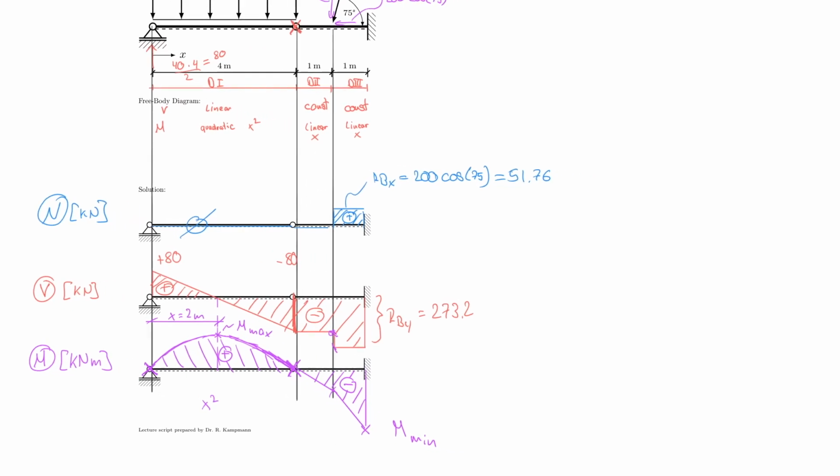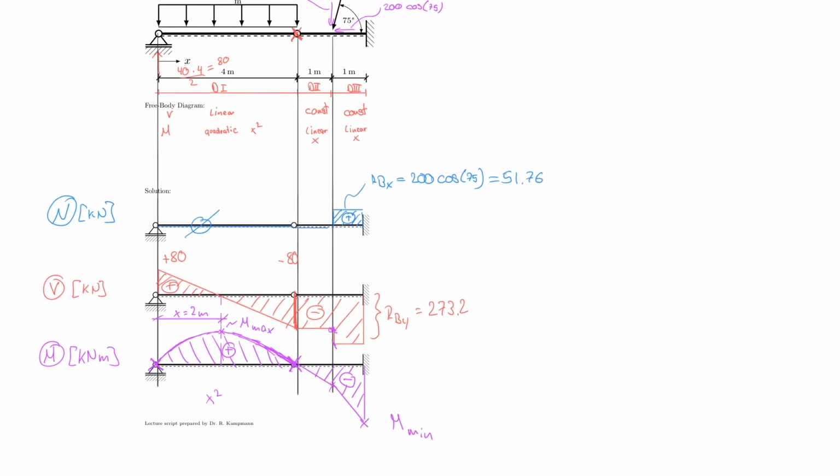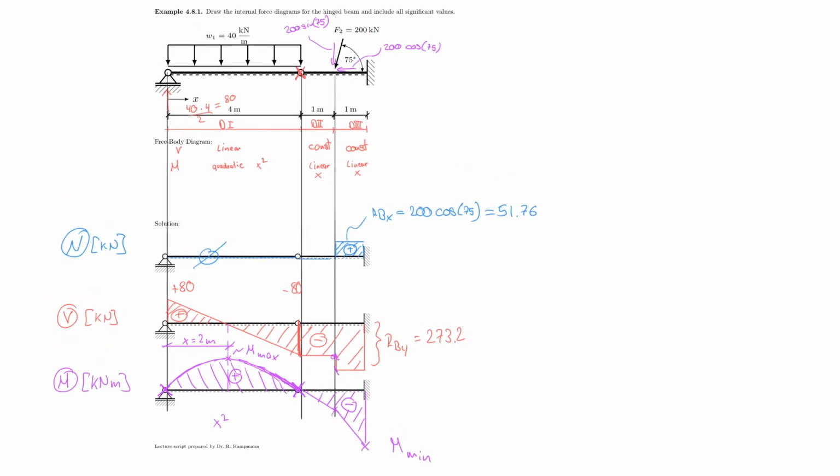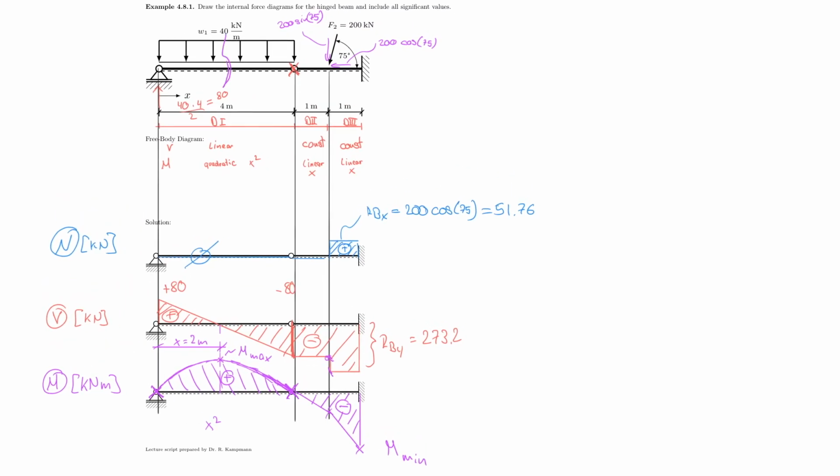Always the same way as I learned in previous lectures, and that is I just make my cut there. Sometimes I can do it in my head, or I can do it, just like drawing it out myself. But for the first portion, I'm going to show this here on the top. I'm going to cut exactly through that point. And so my M max would be equal to the support reaction RAY times 2 meters.